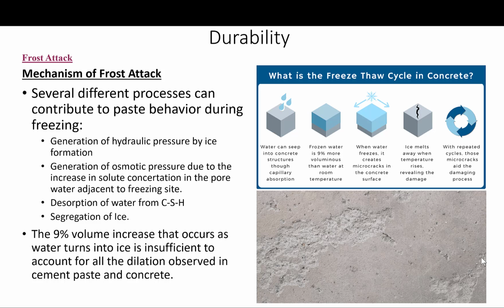Okay, so let's look at the mechanism of the frost action. What happens? Several different processes can contribute to paste behavior during freezing. These are the generation of hydraulic pressure by ice formation, the generation of osmotic pressure due to the increase in the solute concentration in the pore water adjacent to the freezing site, desorption of water from the calcium silicate hydrate, and also the segregation of ice.